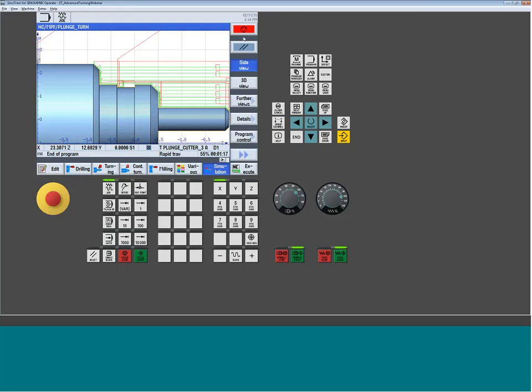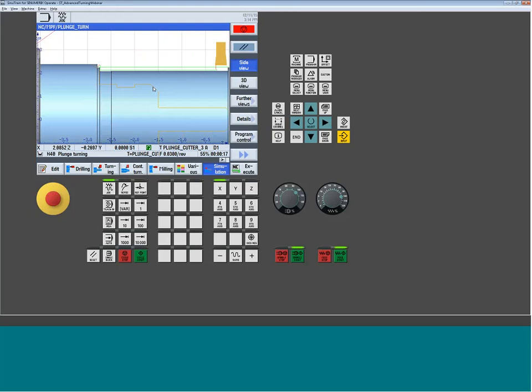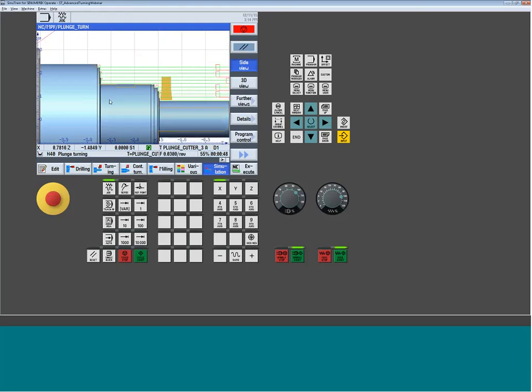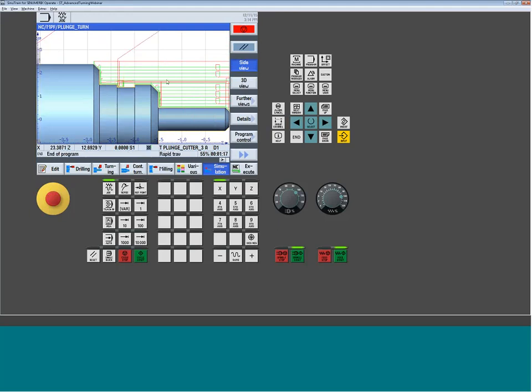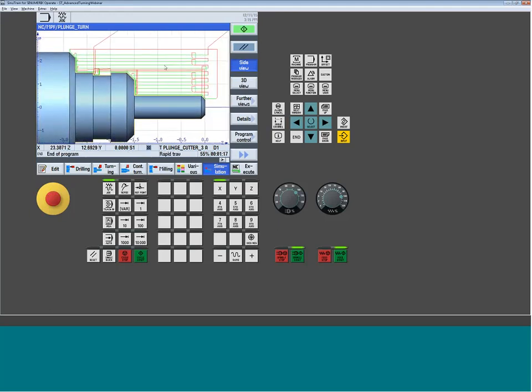So what happens on those tools is as they're machining across, they're actually deflecting a little bit. So we pick the cutter up at the very end to keep that blade from springing back in and gouging or overcutting. So there's a lot of stuff going on here. These little nuances that the cycle automatically takes into account to give you an accurate and viable cutting solution. So it's a pretty cool cycle, and certainly much more efficient. I mean, you can see how many less rapid moves we get here.